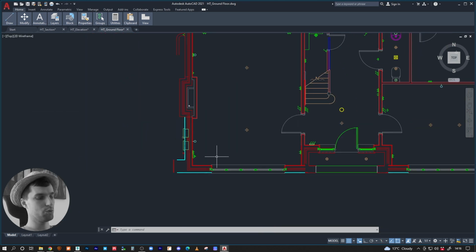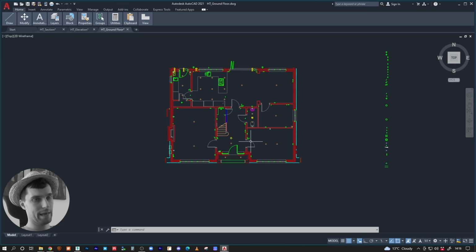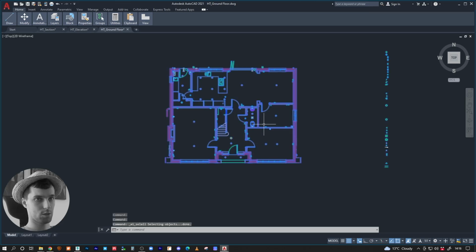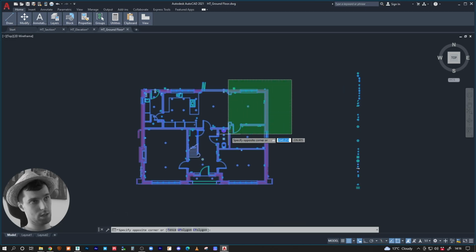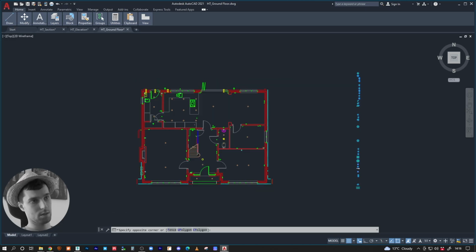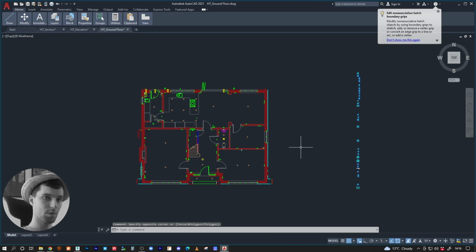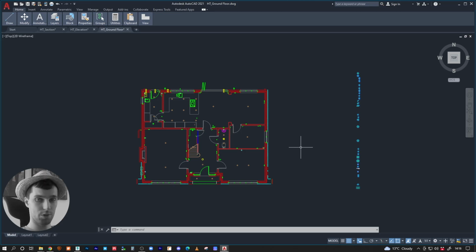So the next thing I would do is Control A, Control plus A. So basically I'm selecting everything in my scene, right? And then I'm pressing Shift, holding it, and I'm just clicking and clicking it again. So what I did here now is I selected everything in my scene, all the drawings, all the objects, everything that is off the grid, off the origin, etc., right? Because you want everything to be at the 0, 0 origin, right? Roughly.